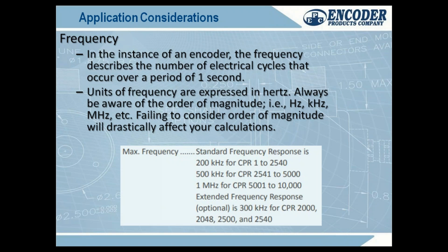The other consideration is temperature. The higher frequency your encoder is, the higher temperature it's going to generate internally. It's the switching, the switching of the 0 to 1, the 0 to 5 volt, or 0 to 12 volt.